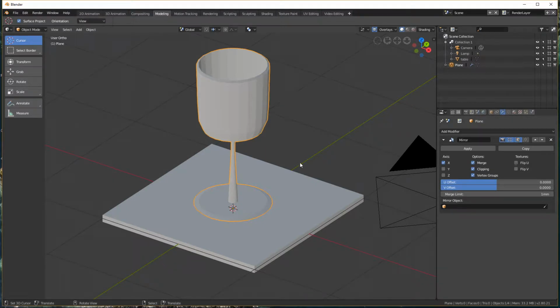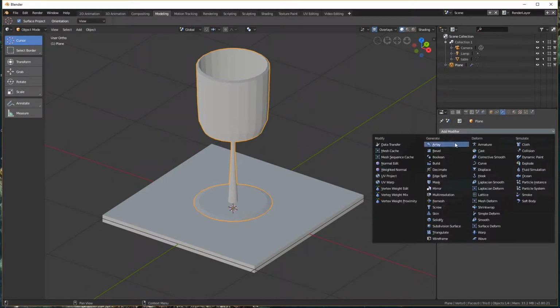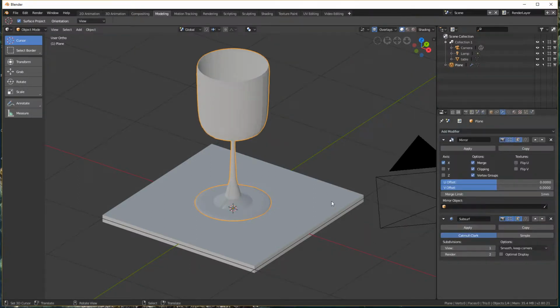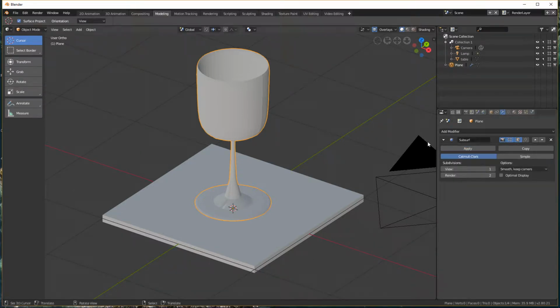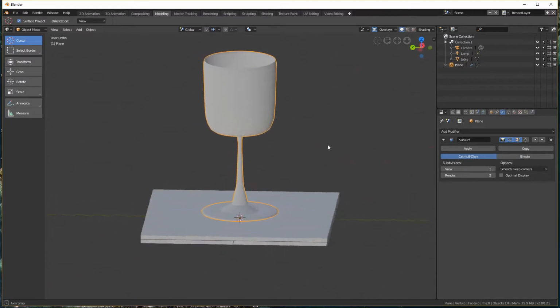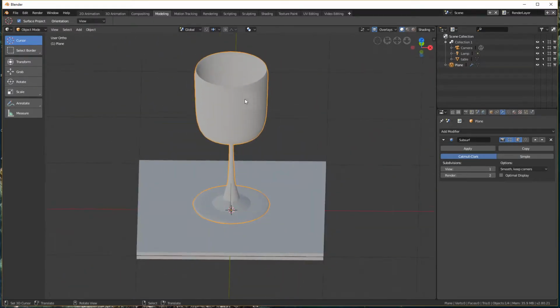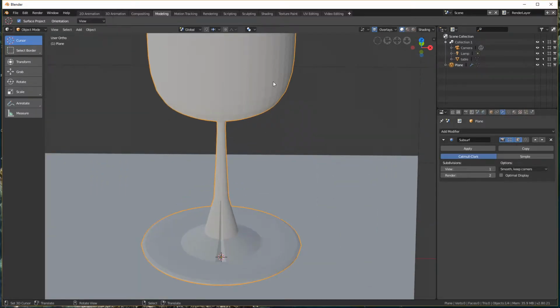I'm going to add another modifier, which is a subdivision surface modifier. And hopefully when I turned it on there, you could see that it got more rounded. So I'm going to apply my mirror modifier. And now I'm going to have a look here at this. So this is not smooth. You can see the individual faces that make up this object. So let's have a look and see if we can...